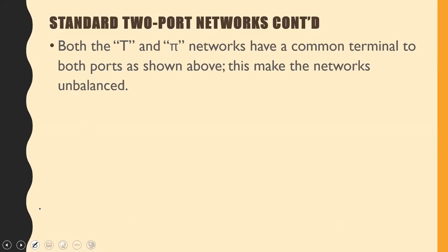Now, the point here is where all the business of balance and being unbalanced is concerned. We say it's unbalanced if the impedance seen going into the upper terminal would be different from the impedance on the lower terminal. And this primarily is of importance for communication circuits.